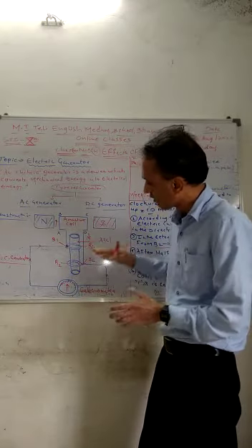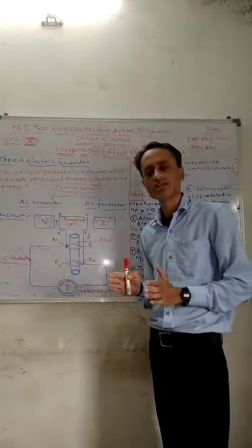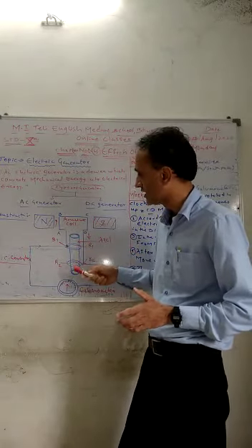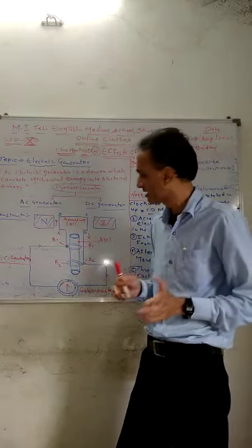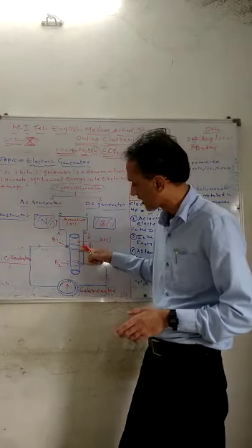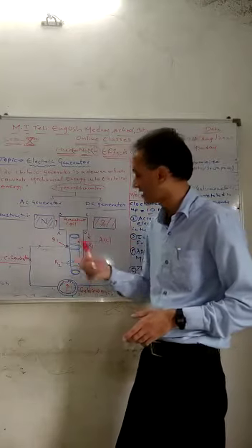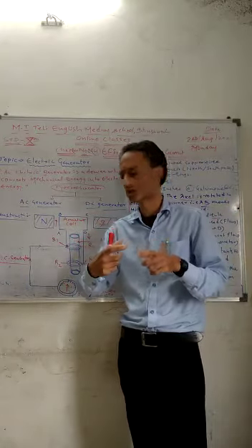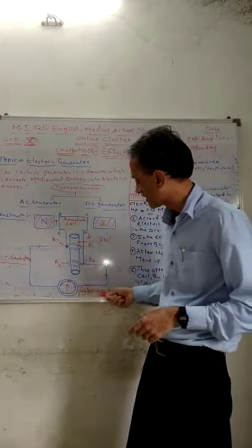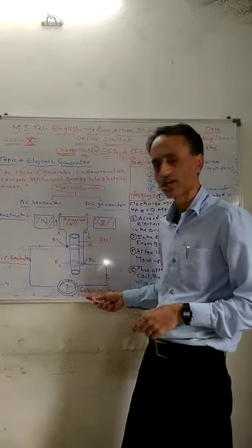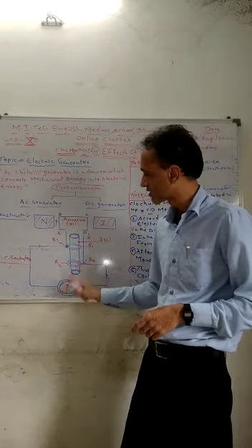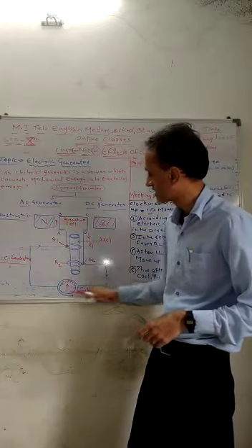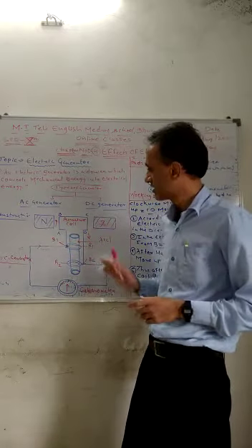You can see the basic difference between the AC generator and DC generator. This is of the rings R1 and R2. In alternating current, that is AC generator, the rings are one after the other and the current supply is alternating. In the DC generator the rings are in front of each other in this position. This is the galvanometer. The galvanometer shows the production of the electric current. It deflects continuously, showing that the current is producing in the alternating direction. So this is the basic circuit diagram of AC generator.